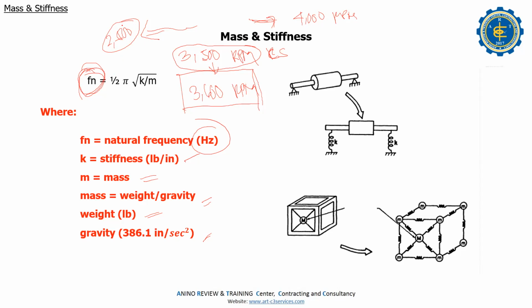Sometimes you encounter a machine that always has high vibration, even when it is new, but you don't know the critical speed. Sometimes the operating speed is 3,600 and the critical speed of the machine is 3,500. That's why, no matter how many times you think it is misalignment or unbalance or whatever, it always has high vibration, because that is the critical speed.